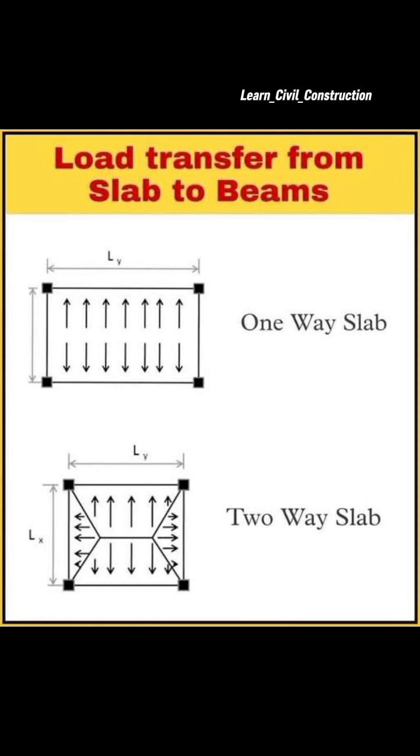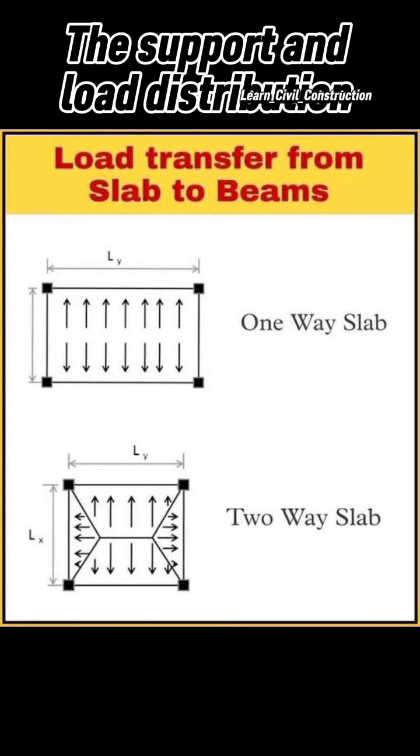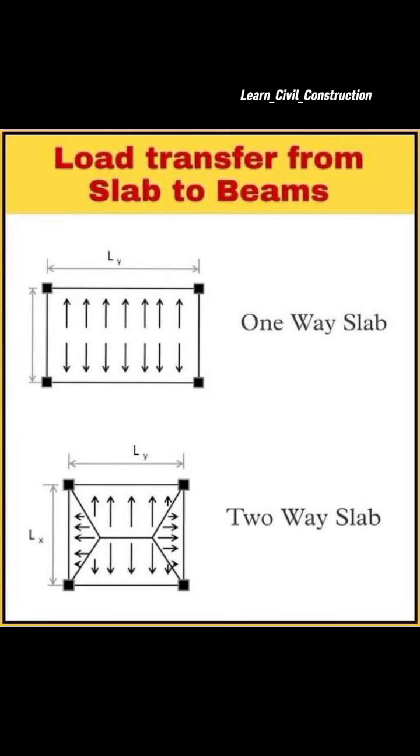But when they say a slab is a one-way slab, what does it actually mean? When you hear that a slab is a one-way slab, they're actually telling you that the longer sides, the two longer sides, are the ones responsible for carrying the load of the panel. That's the two longer sides.